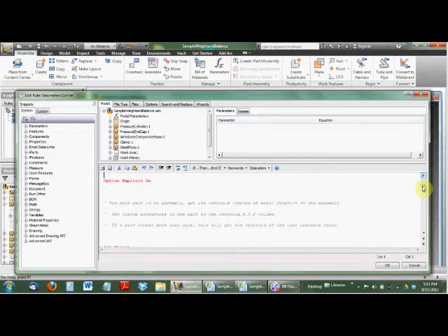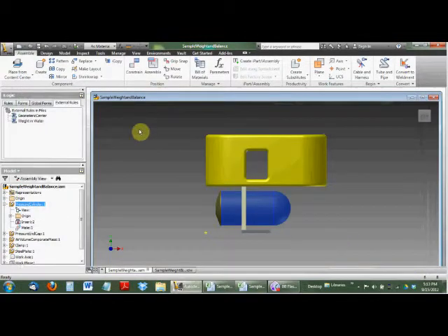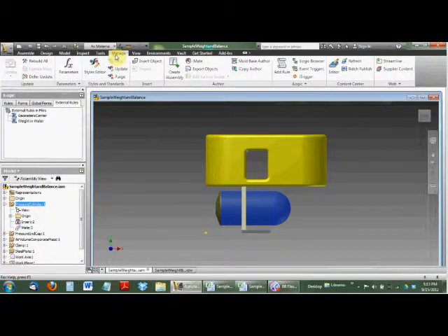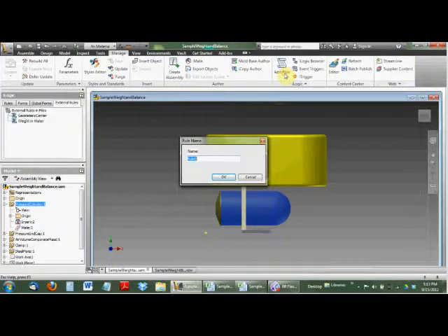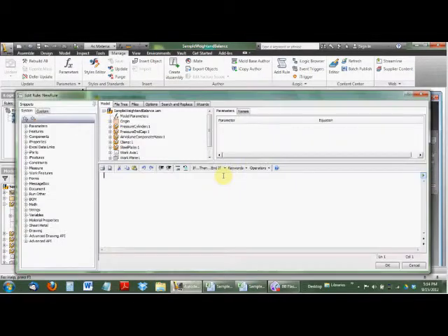And now going backwards just a bit, you get to iLogic by going to the manage menu item, and then you go over here to add a rule. And this is the iLogic browser that puts this little cube up over here. And when you want to create a rule, you click on that. You can name the rule new rule, not rook, but rule, and you just say OK, and voila, this comes up.